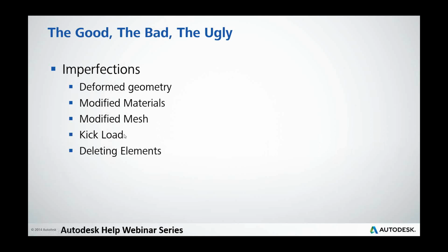One of the common ideas that we try to do is using a kick load, and that's where you input a load out of plane and try to initiate that buckling. We won't be doing that today.